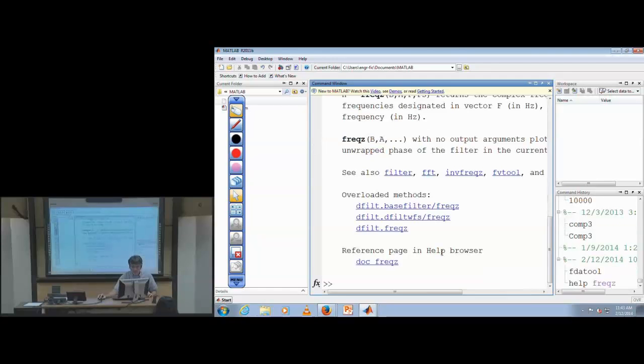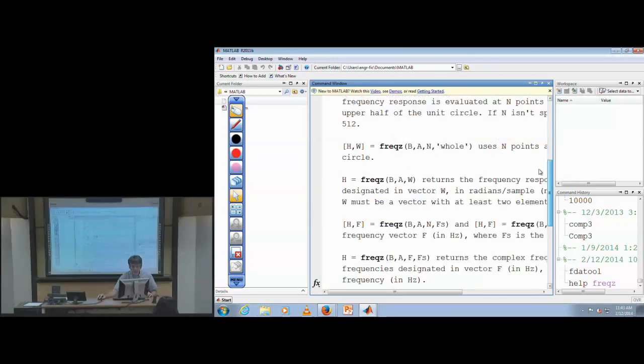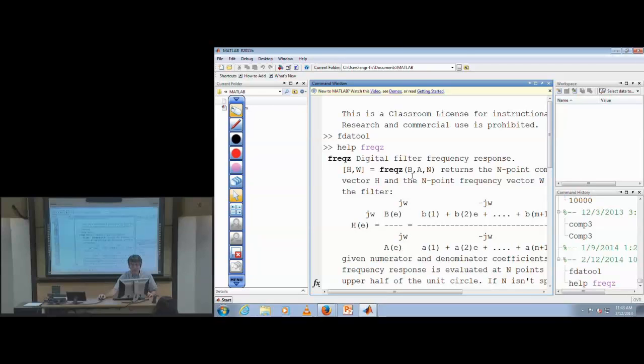Right, so the simplest use of freqz is to just give it a vector of the impulse response. That's the first argument for an FIR filter. And it will give you the magnitude and phase as plots of the frequency response. And pzplot would be the other one that's useful for the pole zero plot for homework 1, 2.1.